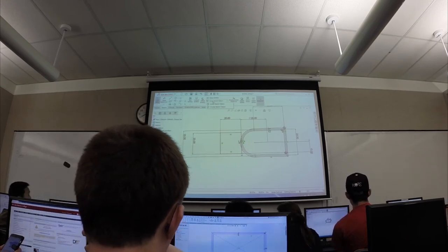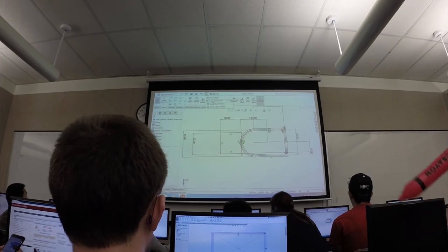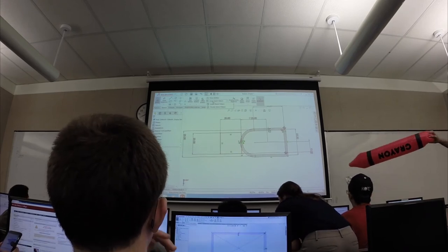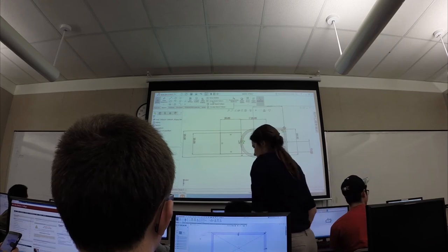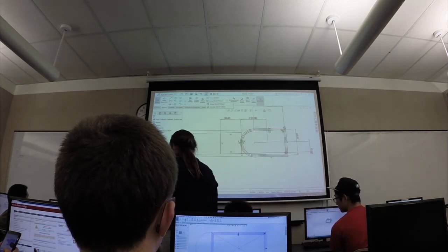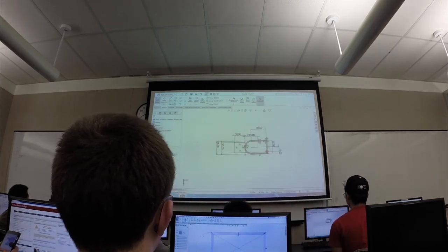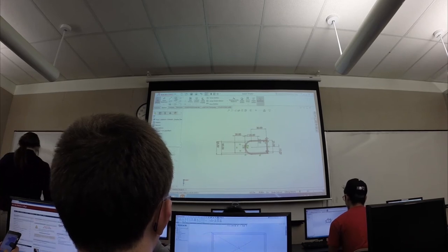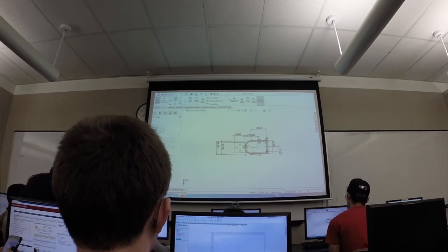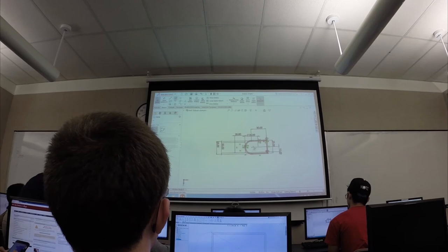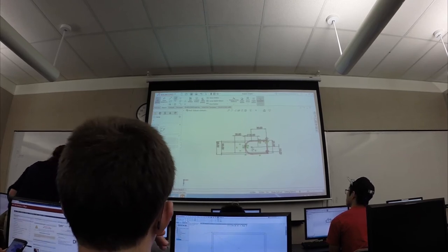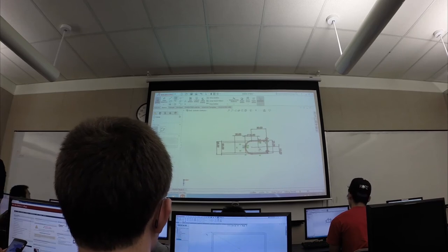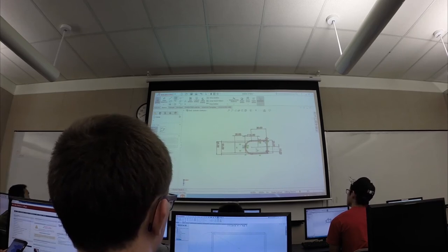A circular sketch, what it does is that you select a center point, and then it will revolve around that center point and create multiple copies of itself. So we're going to try both and play around with it. For the time being, let's click the circle tool, hover over this, don't click on that center point yet. When you hover over that center, you can start dragging out sidewards.